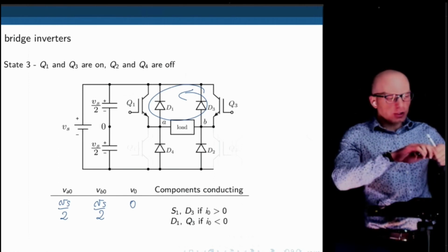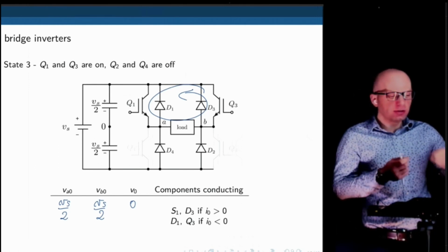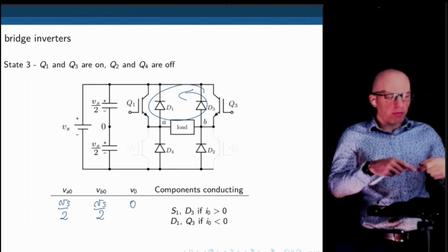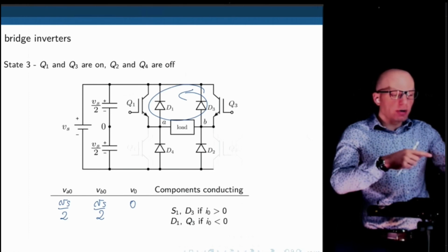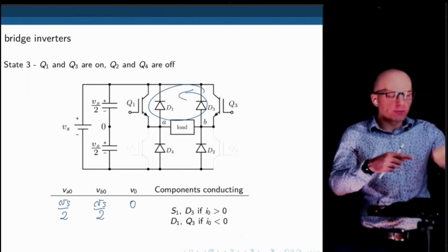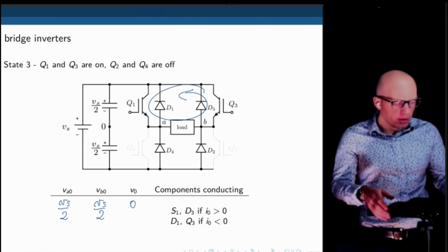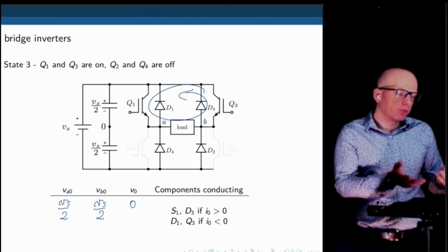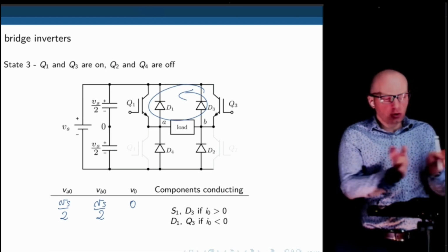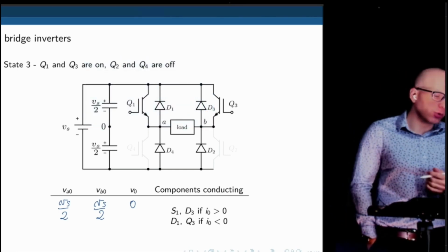If you connect the terminals of a DC motor together and you try to turn the shaft, you see that the faster you turn, the harder it gets to turn, because you have now created a closed loop path for the current. The current you create by using it as a generator creates its own magnetic field that opposes further changes in the magnetic field, and you create a torque that opposes the motion. It becomes like a damper. This is called a braking or damping mode for a DC motor, when you short its terminals. You can use it to slow down a DC motor, amongst other applications, and restore energy to a power source, for example.